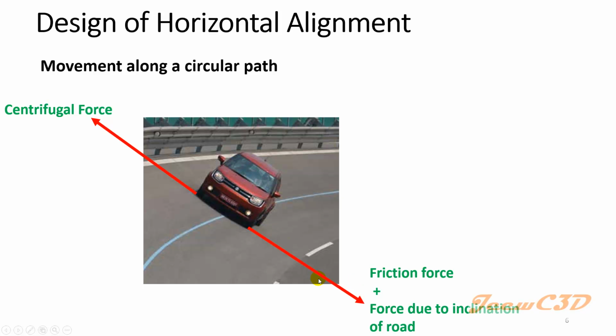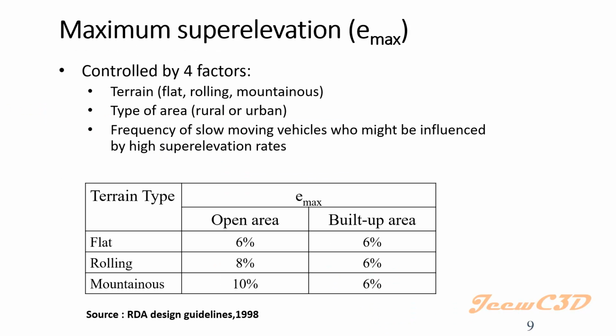So if you have a high inclination, this load component will be high and it might cause the heavy vehicles to fall or topple on the road. You may have seen this on roads. Sometimes the heavy vehicles fall apart or are toppled on the road because of this super elevation effect.